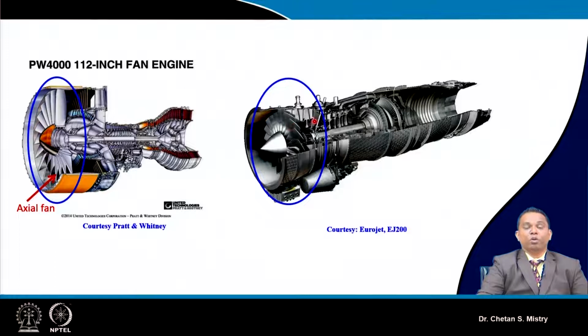Okay, so for engines, conventionally people used to say for a high bypass ratio engine, the fan is going transonic. For a low bypass ratio engine, my LP compressor or the fans are going to be transonic. Sometimes, maybe for the LP compressor or maybe a few early stages of the HP compressor, they are also of transonic nature.